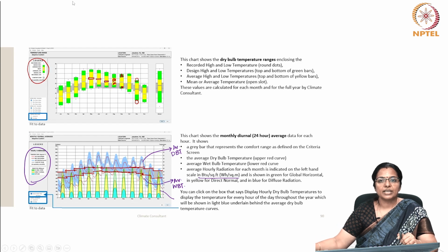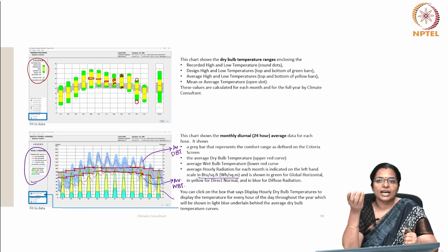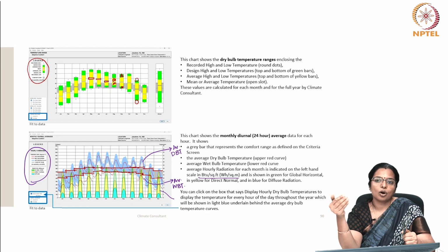So, when diffuse radiation is higher, it usually means that the sky is more overcast, and so direct normal beam radiation will probably be cut down. Thus, total or global horizontal radiation will be reduced. Global horizontal radiation is the sum of diffuse radiation from the entire sky vault plus direct normal radiation from the sun times the cosine of its angle of incidence to the ground.